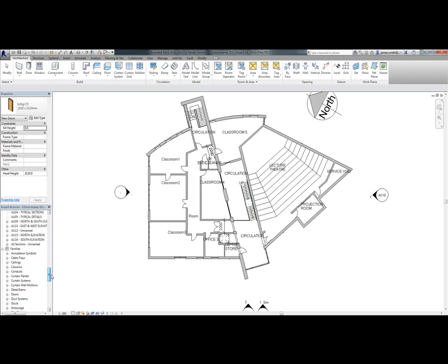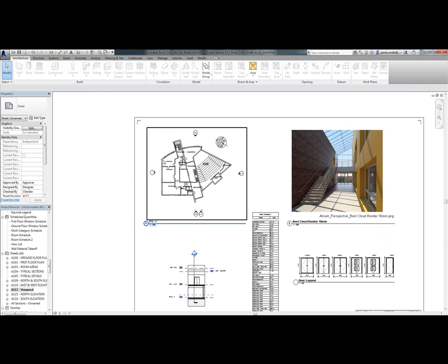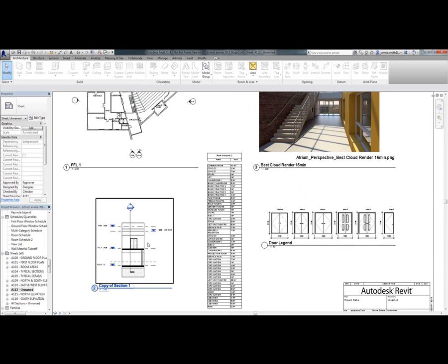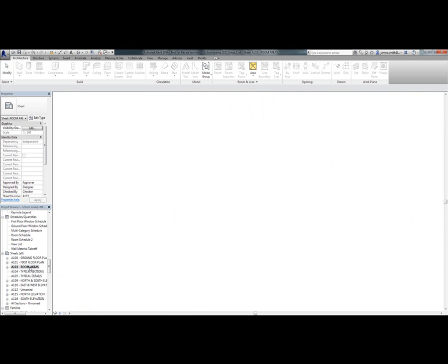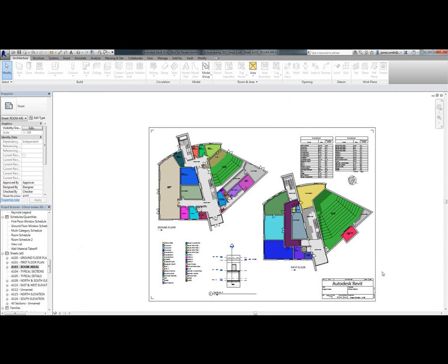Go back to my new drawing. It's all been updated. All the doors and the uses are there. So I now know this associativity is all up to date. I haven't had to worry about going through and updating however many drawings this will affect, because every one I go to is now up to date.